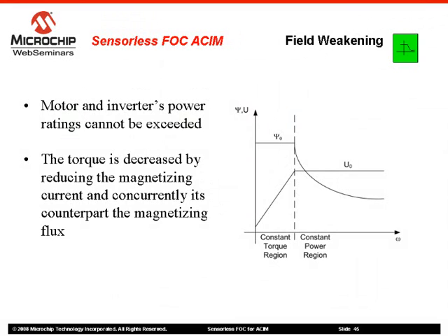When exceeding the nominal motor speed, the rotor flux must be weakened. A mechanical speed increase will require a frequency increase of the stator currents, but this must be done with respect to the simple volts over Hertz equation. Since the voltage cannot be increased over the nominal value, the increase of speed must be done sacrificing the overall torque produced, keeping a constant power curve.